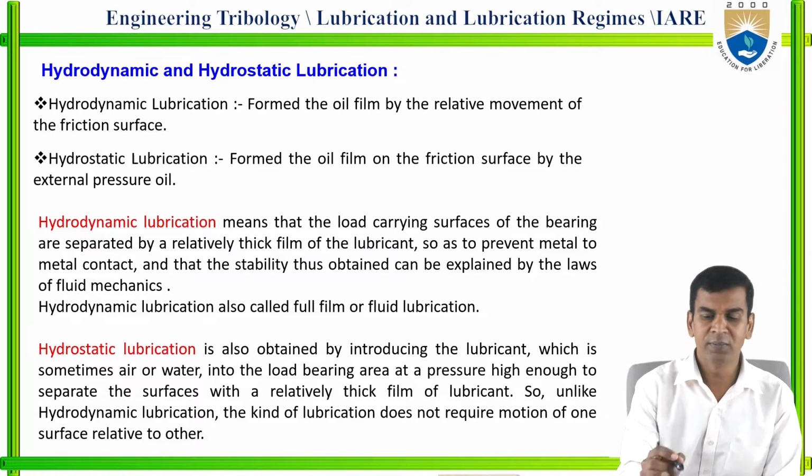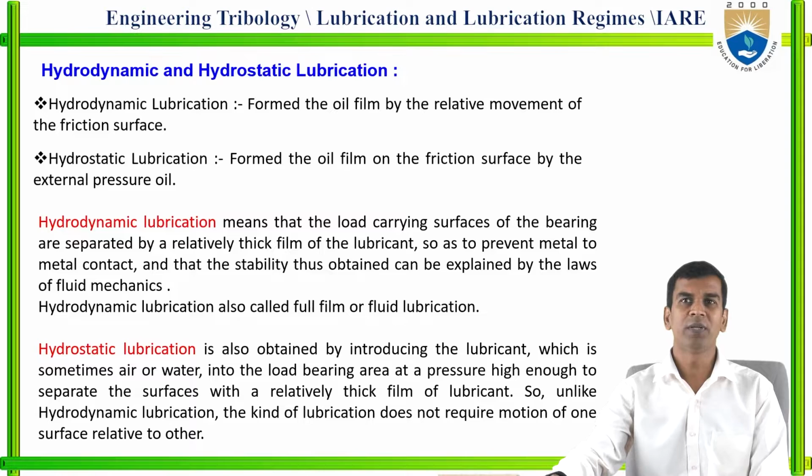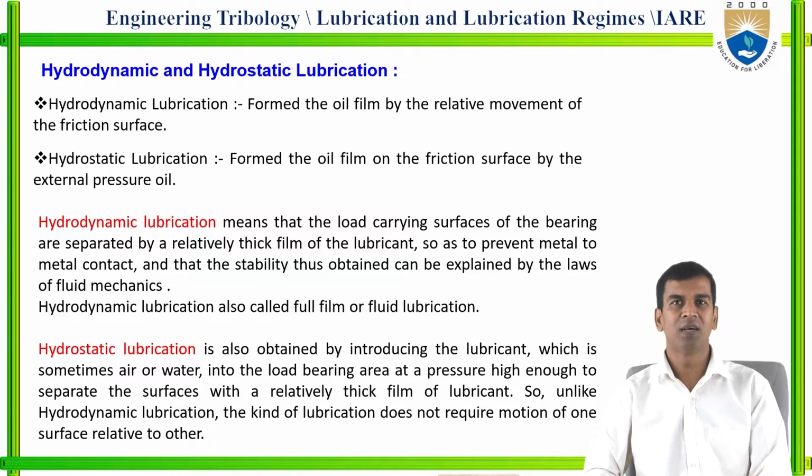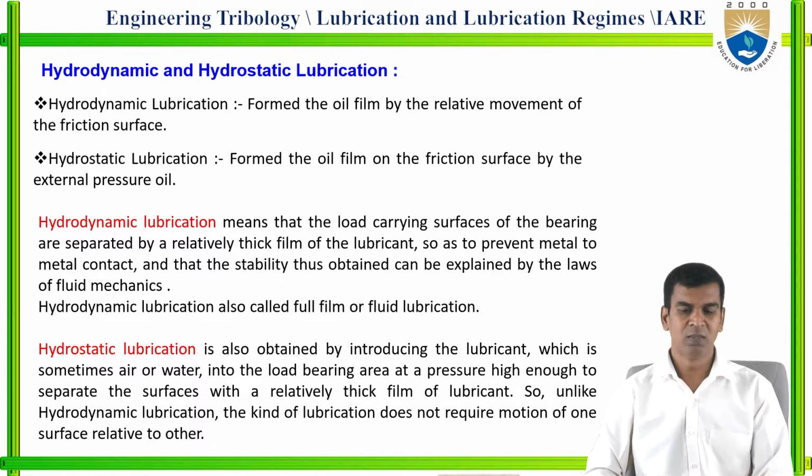Next, hydrodynamic lubrication means that the load carrying surfaces of bearings are separated by a relatively thick film of lubricant so as to prevent metal to metal contact, and the stability thus obtained can be explained by the laws of fluid mechanics.